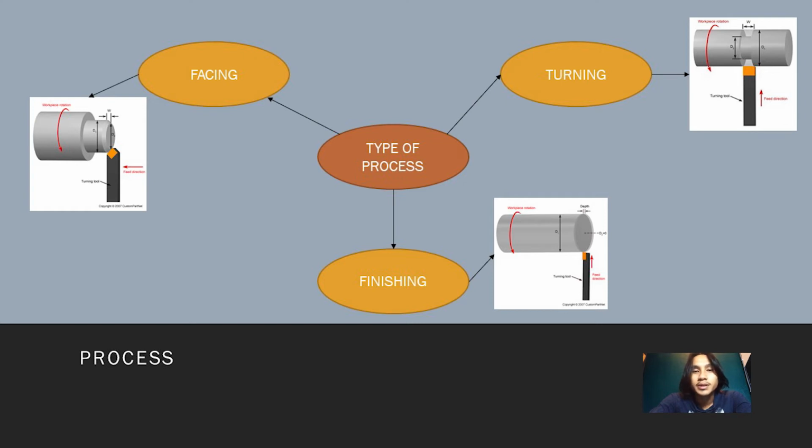Finally is the finishing operation. Finishing is a process that produces a clean surface finish and accurately sizes the workpiece. The type of surface finish generated can be influenced by factors such as the condition of the cutting tool, the bed, the stiffness, and the workpiece. We have to know that finishing is the last phase in the manufacturing process, and it is used to give aesthetics as well as environmental protection. For pieces that must mate or seal, this process will be employed to minimize surface roughness beyond the capability of machining techniques. That's all about the three processes of the lathe machine.